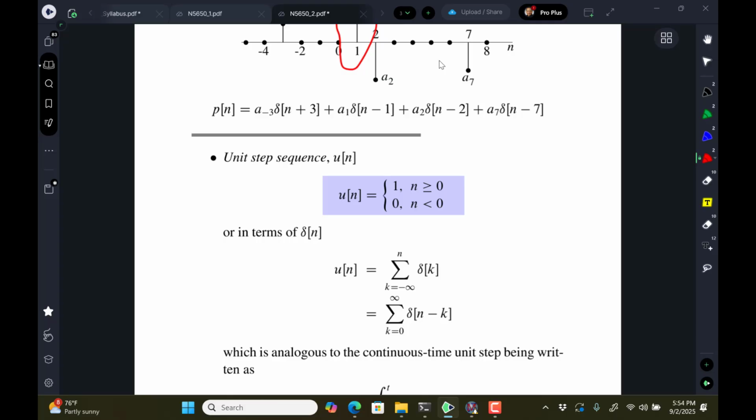And in analog signals and systems, that's because can a function instantaneously jump from one value to another? Can it really do that in physical terms? It can't. There's always parasitic capacitance and inductance that's going to keep it. It just can't change like that. The mathematics, though, lets you do that, and that's where the math and the physics kind of wrestle with each other.